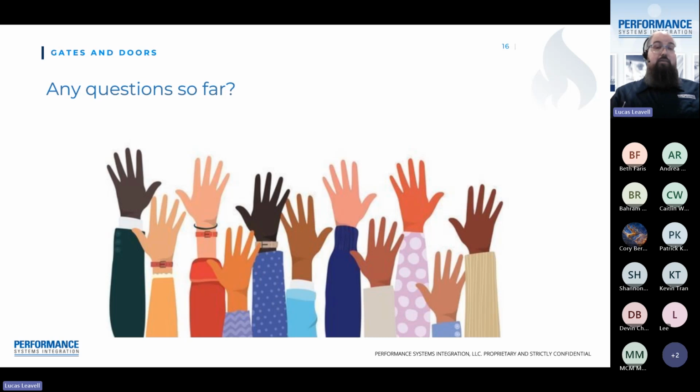Chimneys will lead to any fire that is down in that environment getting significantly worse. But also, now you have an entry point into the interior of your building for things like rodents and pests, insects, outside environments. Let's say that your garbage room is actually just an exterior of the building where the dumpster is. Well, now you could have a raccoon climb up in there, or you could have moisture intrude up inside. Not to mention any number of unpleasant smells. If you do have a circumstance like that where you're unsure if the garbage chute has a proper door on it, especially at the bottom of the dumpster, it does need to be addressed and a new one should be installed.